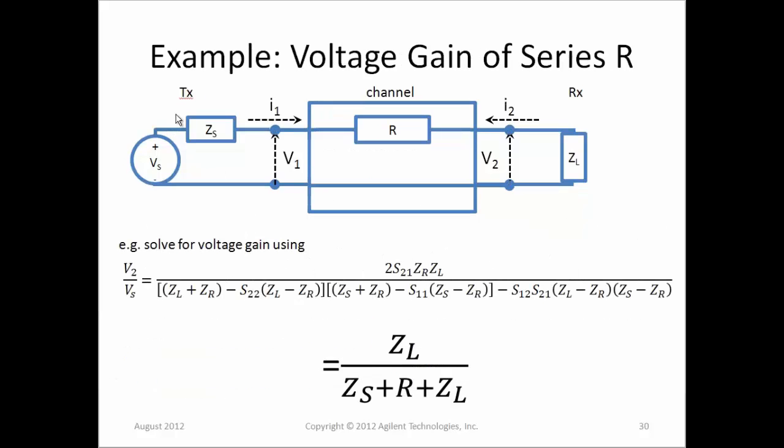Again, extra credit if you want to plug through the algebra and just plug it into this equation. If you had, say, a series resistor and the manufacturer gave you the S parameters for this two-port network with inside the black box just a series resistance, if you take the values that we had before for a series resistance, you'll remember that from slide 27, plug the numbers into this rather large equation that you can derive with some effort algebraically.